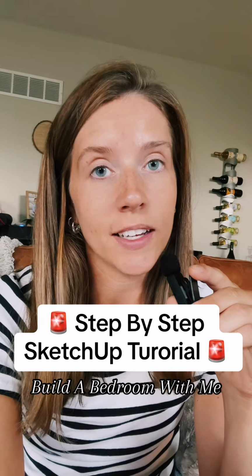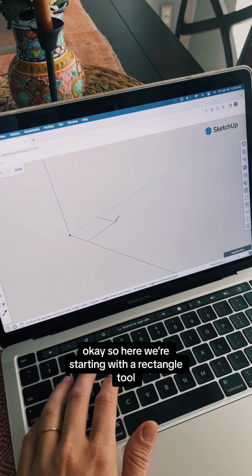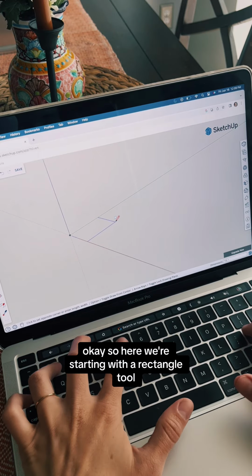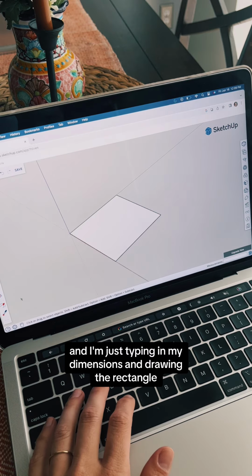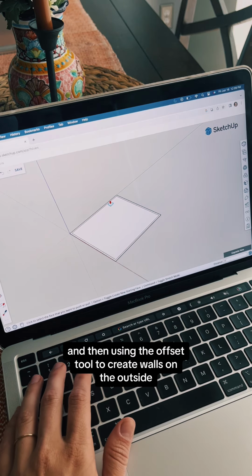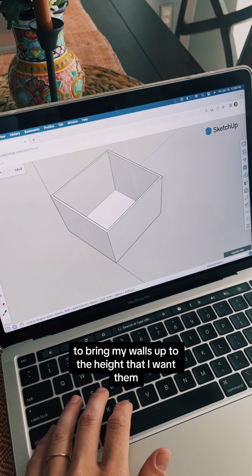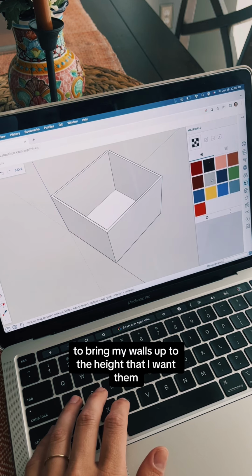I'm going to show you exactly how I model a 3D room in SketchUp Free in 2 minutes. Okay, so here we're starting with the rectangle tool, and I'm just typing in my dimensions and drawing the rectangle the dimensions that I want it. I'm then using the offset tool to create walls on the outside, and I'm using the push-pull tool to bring my walls up to the height that I want them.